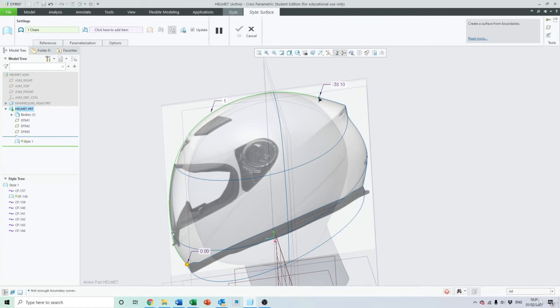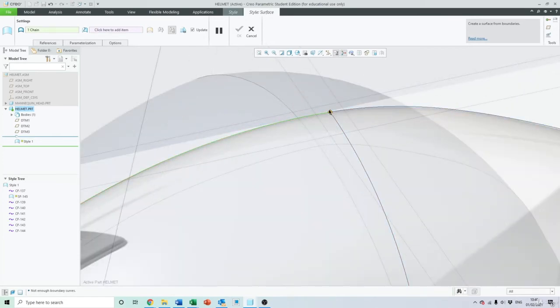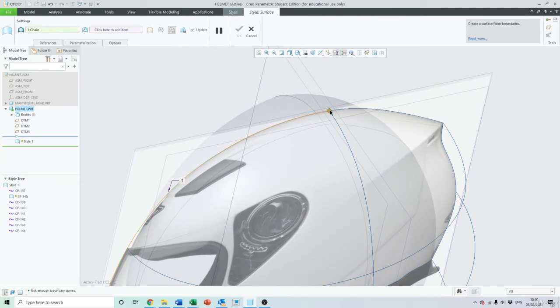We can, while we're dragging, hold down the shift key, and you see how the button changes from a dot to this broken square here. Holding down the shift key, if we move along and we reach this cross section between this curve and the other curve, it snaps and the square solidifies and turns a green color.